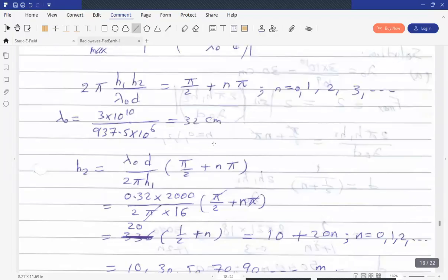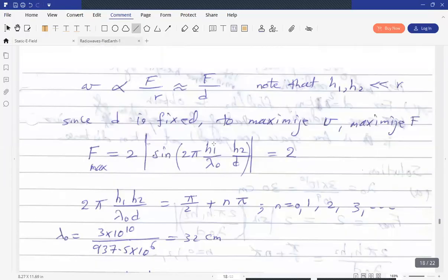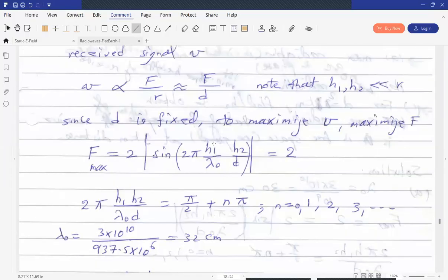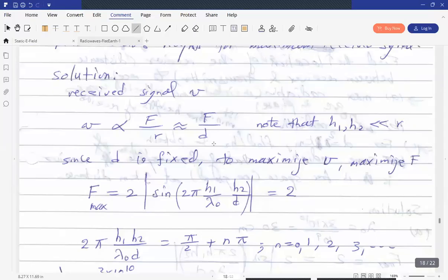I have a question. When we talked about the refractive index, for each atmospheric level there is a certain n, the square root of epsilon r. Now, when calculating P received and the path gain factor, we don't take this into consideration, right? No, because we said that instead of the actual radius of the earth we put the equivalent radius.